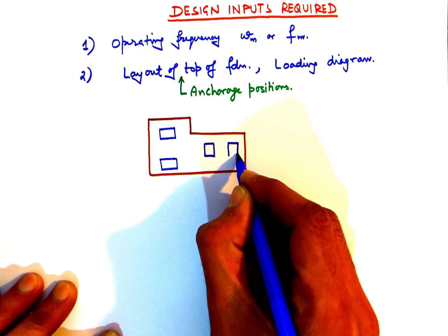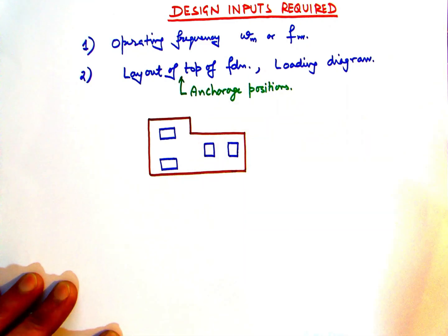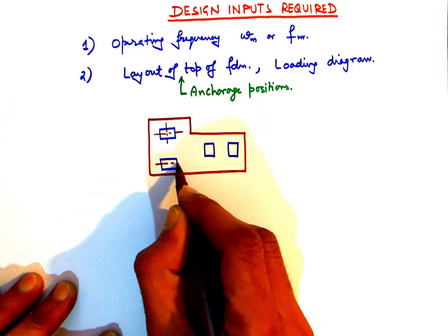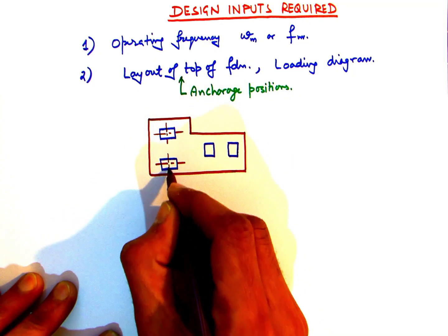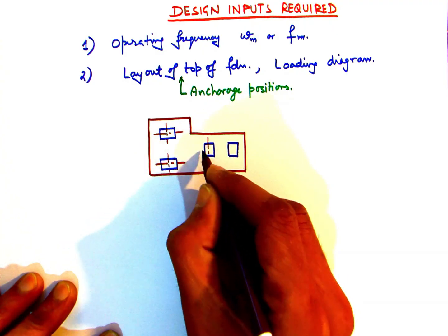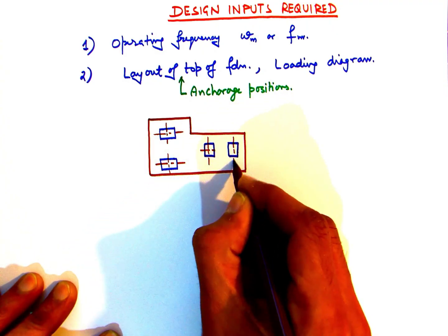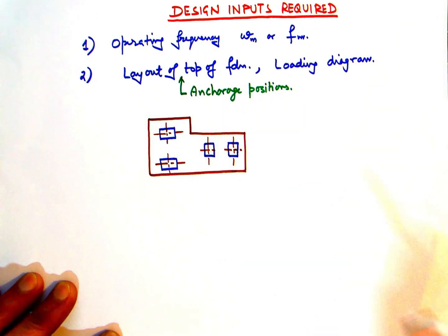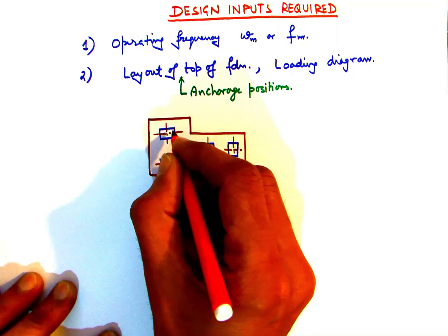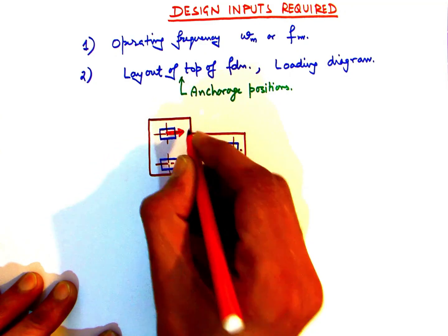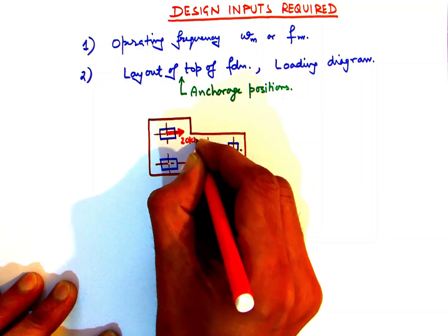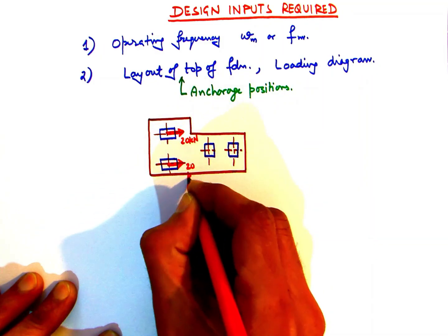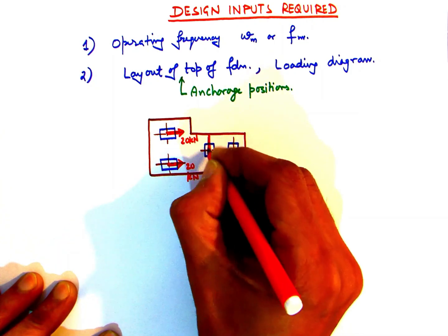For example, here we are showing a typical sketch of the layout expected by the manufacturer of the machine. He has also specified what should be the shape of the top of the concrete. So this shape and the locations of the anchor bolts or the pockets are to be adhered to by the structural engineer. Of course, these dimensions are tentative.